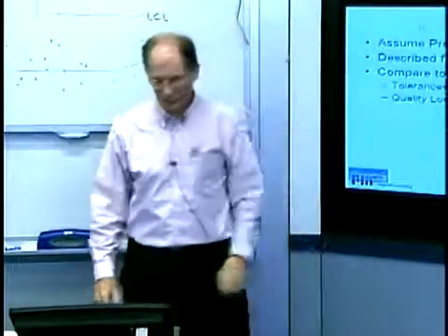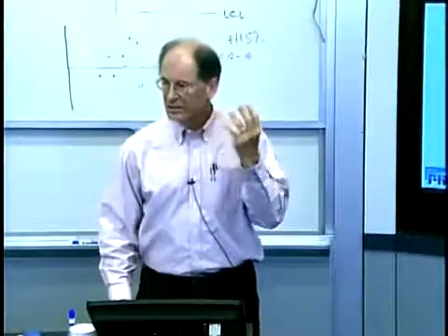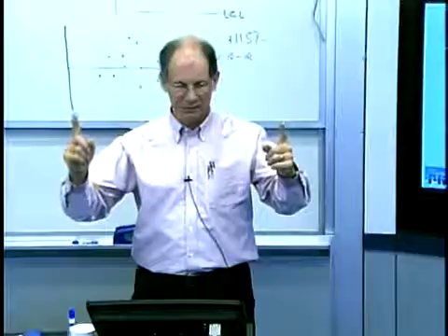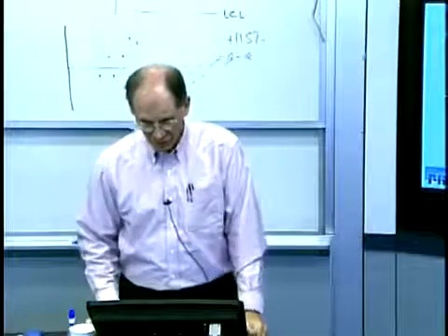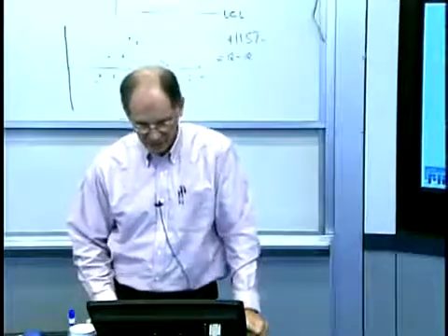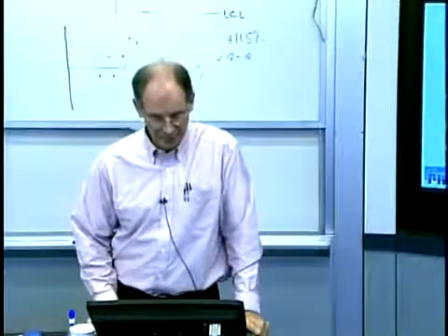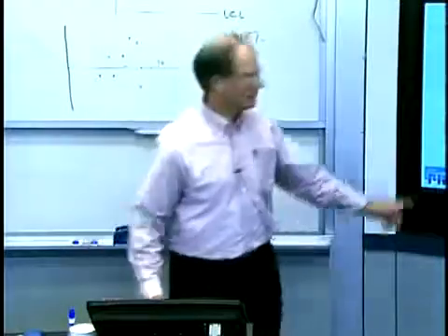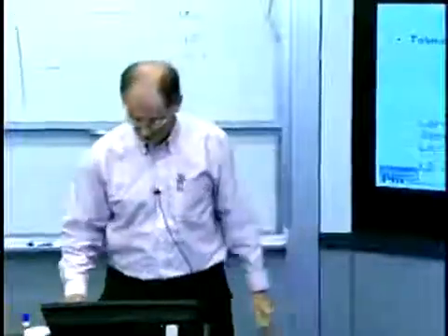And there's also this concept of quality loss, which is a better way, in some ways, of looking at design specifications. The simplest design specification we can think of is an upper and lower limit, a tolerance. If you can make me a part that falls between these two limits, it's a good part. You can think of that as a nominal value, a target, and then an upper specification limit and a lower specification limit. Not control limit, but specification limit. Tolerances basically say anything in there is a good part, has equal quality, if you will.